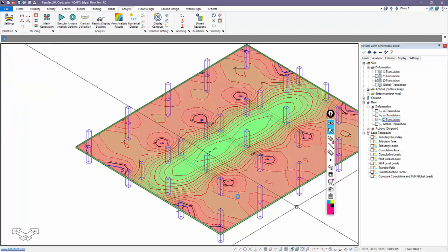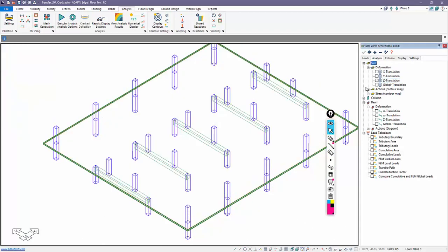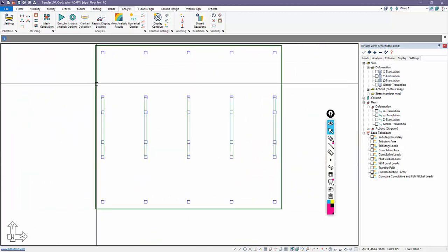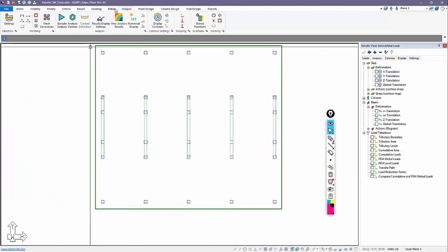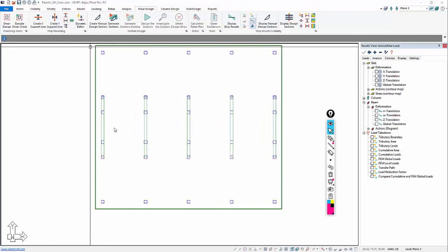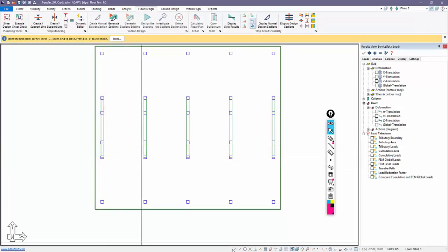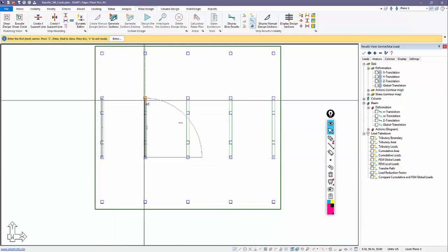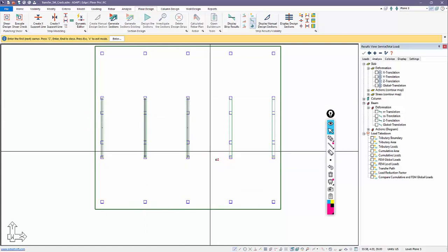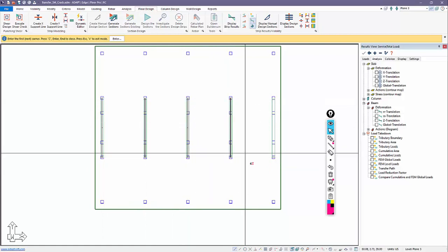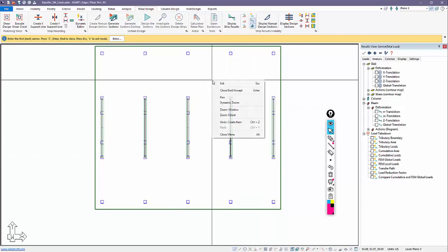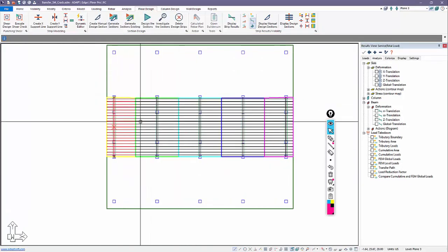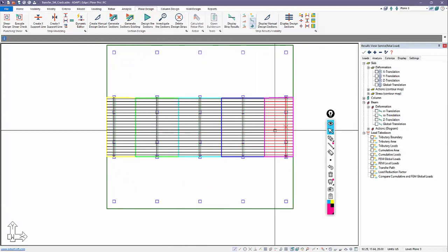We can also design the beams based on this particular run. So if I, for example, create a support line on these beams, let's do that. We'll go to Y direction support line. And I'm using, again, version 19 here. One nice thing about 19 is you don't have to use any splitters to obtain the proper geometry for the tributaries. If I generate the sections, you can see the program creates my design cuts.